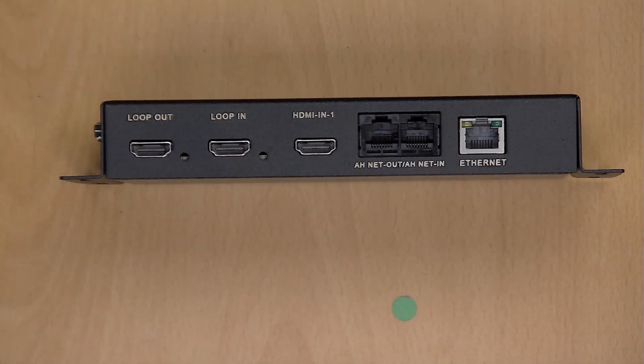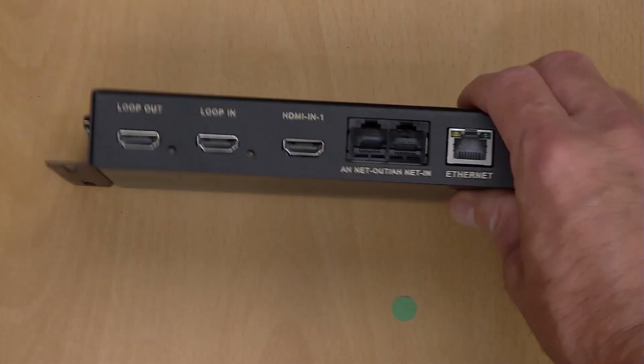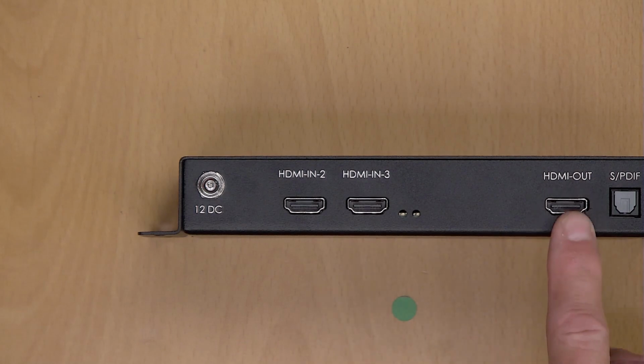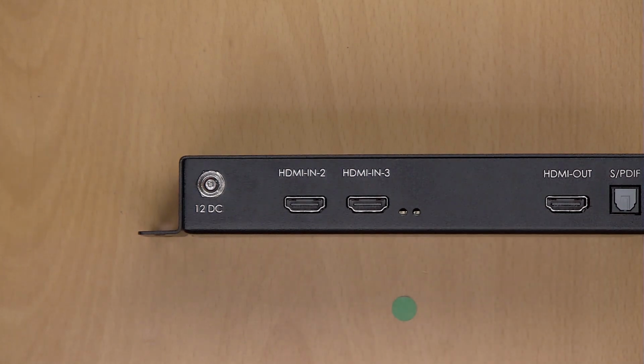So one of the things that is important when we're talking about DynamicShare is that the looping has to be done using the in and out. We cannot take the out input and go to a loop out and put it into a screen. Maybe it will work, maybe it won't, but then you don't have the whole setup closed. It has to be a closed circuit. So that's not an option. You have to use the HDMI output that you see here.